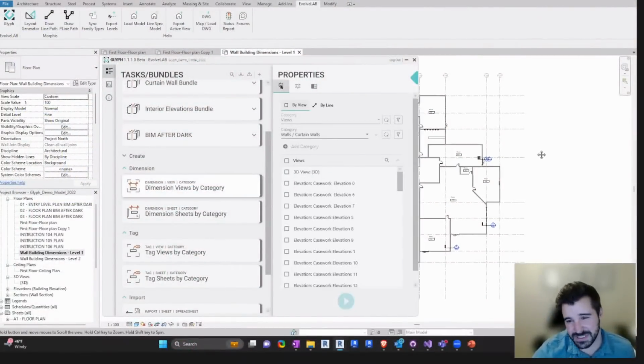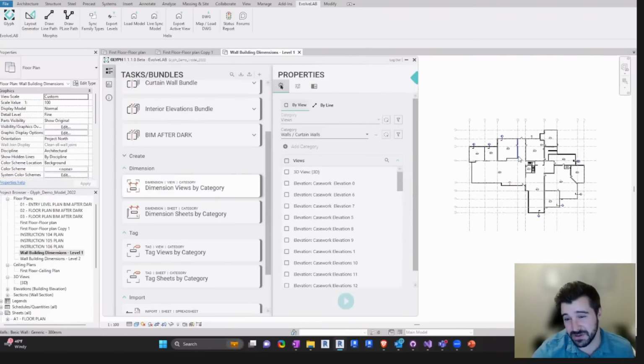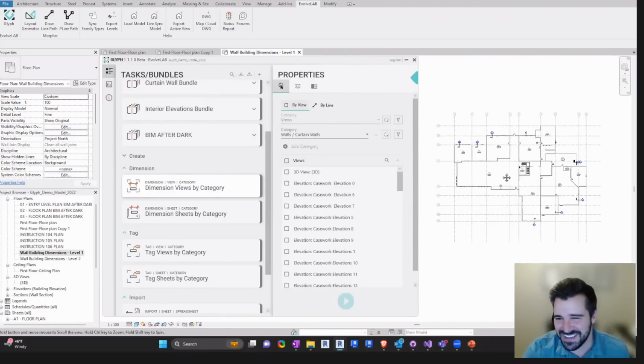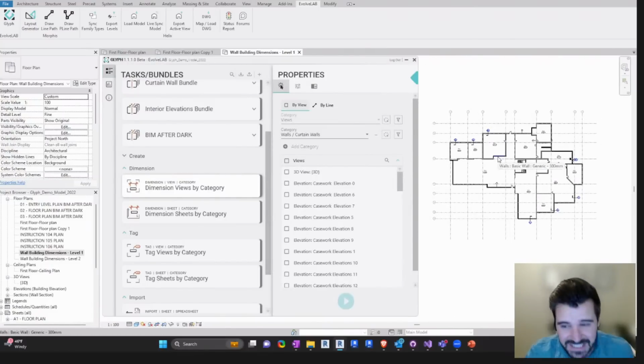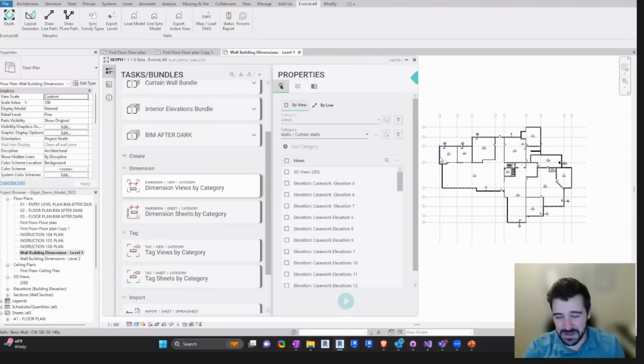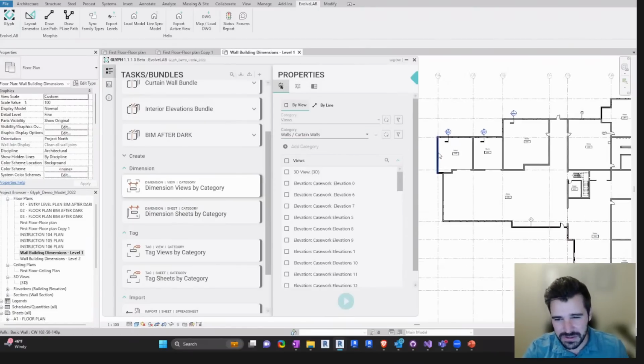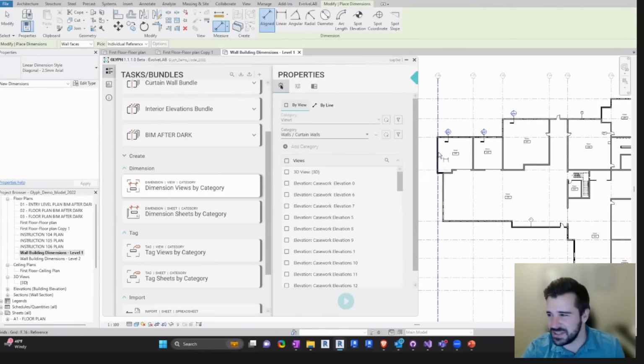Perfect. Yeah. I will say the dimensioning one, it's one of my favorite ones, personally. Because dimensioning in Revit, at least in my opinion, might not be the most fun task. Like, for example, we are talking about wall dimensions, right? You have to click tab, tab, tab, tab, tab, and then if you miss it, you've got to go tab, back. Oh yeah, oh yes. Yeah, I think we all know that for a very long time.